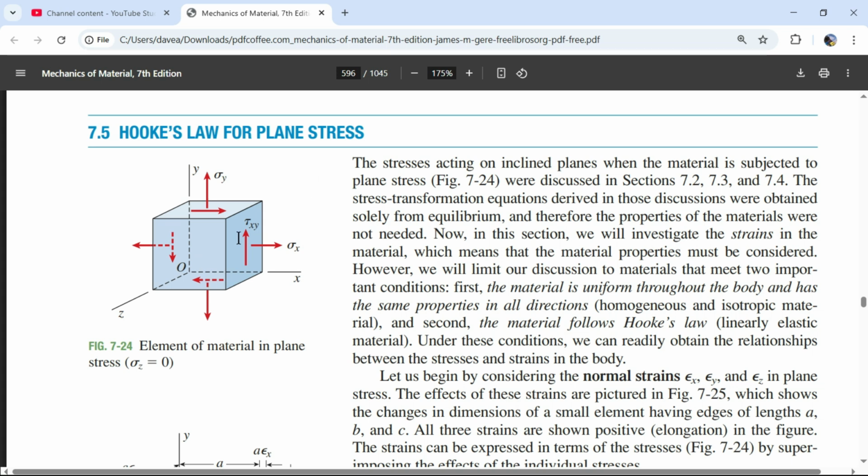On a cut, you can only have a normal force and a shear force, that's resisting. A better way to say that is, if we open up this cut, we have to have a force still in this direction. So if this is pulling this way and we make a cut like that, we have to have a force on that surface in this direction. And this direction, in relationship to that angled cut, is going to have a normal component and a shear component to actually get to that vector, to meet that equilibrium. And so, hell yeah, you introduce a shear when you angle this cube.